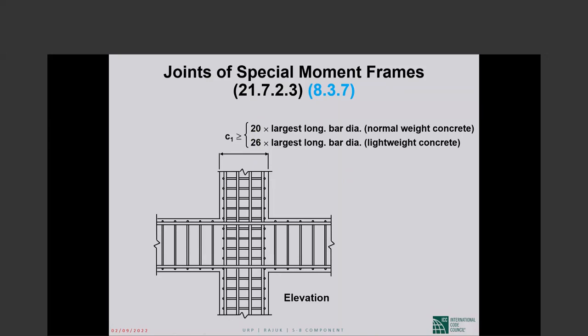Okay. Lightweight concrete columns, I don't know how common they are. I think they're becoming, I don't know. I don't know about Bangladesh either. We had nothing, so we multiplied the 20 by 1.3 and got the 26. That one is probably not important for you. Now when this condition is violated, you do not go for larger columns, you go for thinner bars. So the interior column dimension shall be no less than 20 times the largest longitudinal bar diameter.